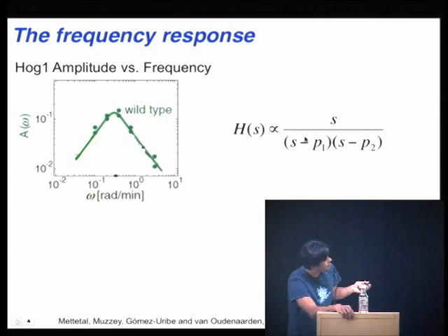So because this is proportional to s, that tells you that the steady state is 0, regardless of the inputs. It doesn't matter what type of step input you'll have. This would predict that the steady state will always be the same as the initial value. And that's actually a very hard function to get to if you want to construct it.